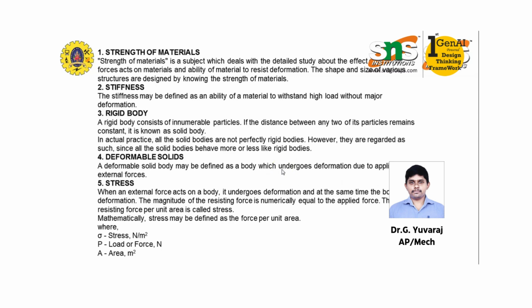And the major topic of this unit is stress and strain of the deformation. Here stress is nothing but this: whenever an external force acts over the body, because of that some resistive force is induced. That is what you call stress. If you are going to calculate the stress, we just need to take the amount of load acting over the body with respect to the particular area. So the stress is equal to load per unit area, or force per unit area. That is what you call stress.